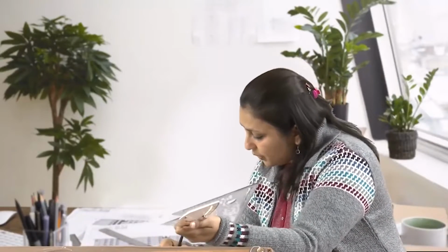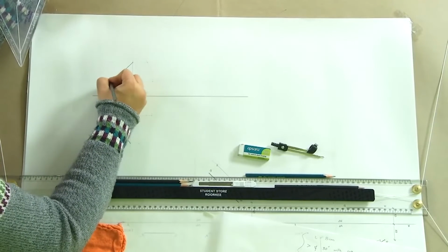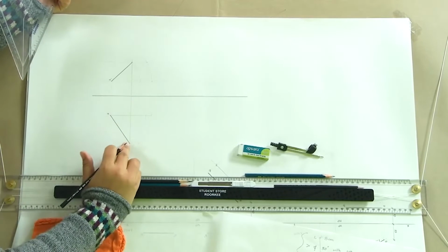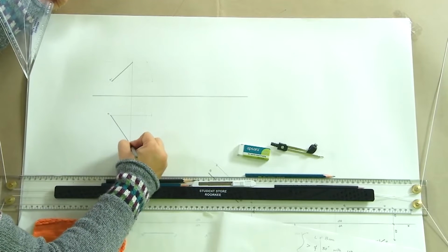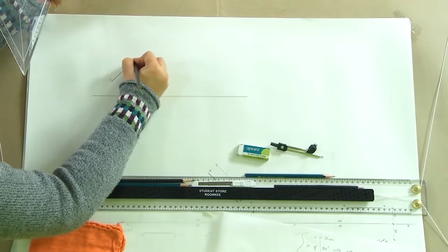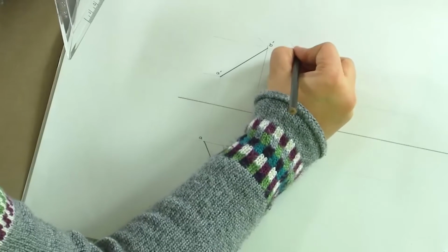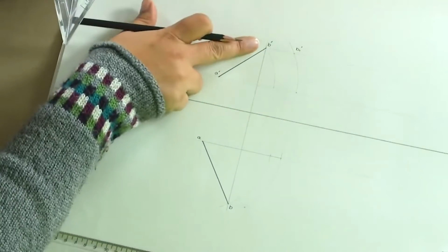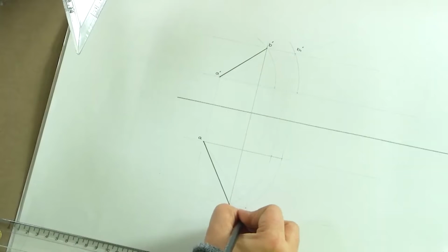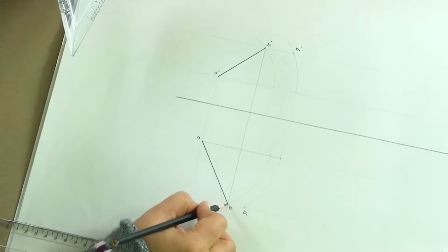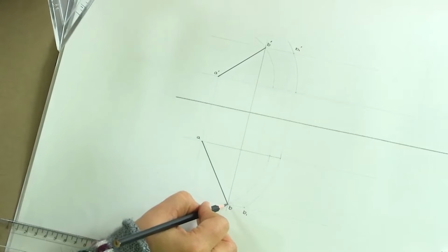We have this point A and we have this point A dash because it does not change. The final one in the plan is the point B, and the final one in the elevation is B dash. Prior to that, what we got was this line B1 dash, which we drew before we arrived at B dash, and we had a line B1 which we arrived before we arrived at the final projection.